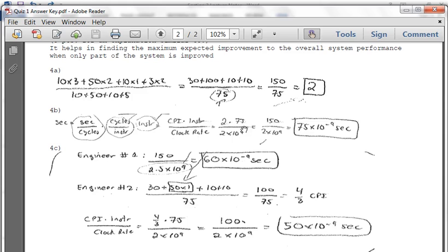So if you're doing a tri-state buffer, and I say, all right, so I have entity tri-state buffer, and I know the inputs. So I have A and the enable signal as in STD logic, and F as out STD logic. So you can show me how to build an entity. That's the key part.